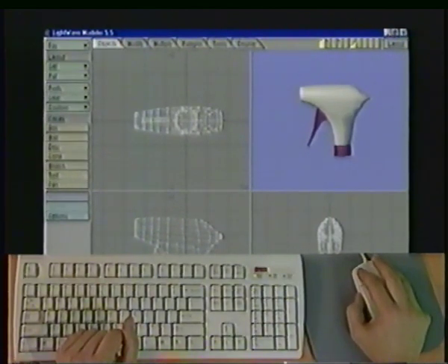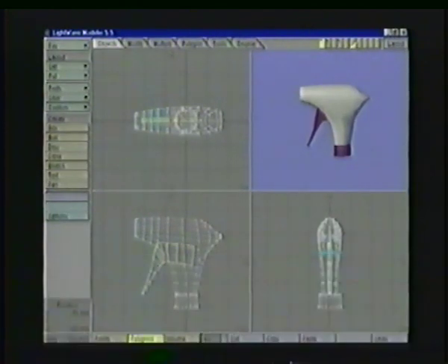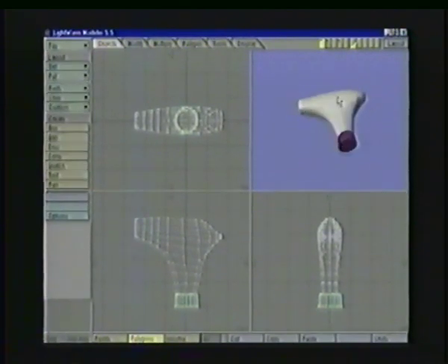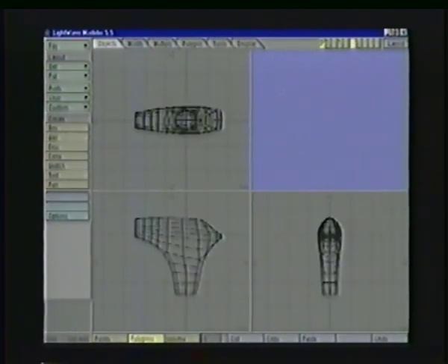That's a simple thing to make out of a cylinder or a disc, and this I'm going to select. You can see they just drew the polys and extended that with the extrude tool. I'll delete that. And this collar is simply a disc with some beveling on it to make the little collar. I'm going to delete that so it's out of the way so we can see exactly what we're trying to work on. I'll swap layers with the apostrophe key again, and we're ready to start with the box tool.